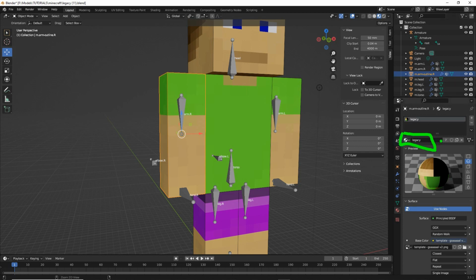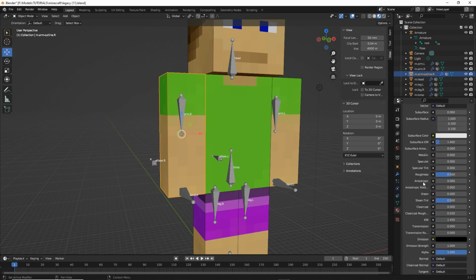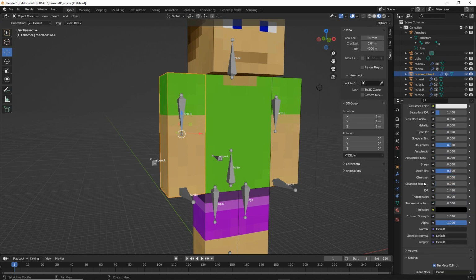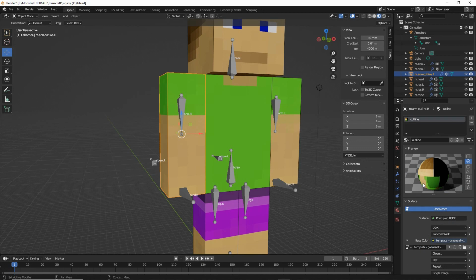Once it does that, we can then edit the material to assign the black color. So we remove the image and assign a black color to it. So click on the button. That creates a new instance, so note the user button has disappeared because this is now unique. So let's just call this outline. So again, it's carrying the same properties, so it's basically duplicated them across.